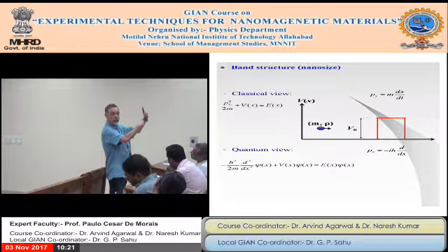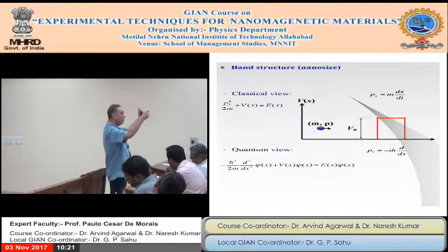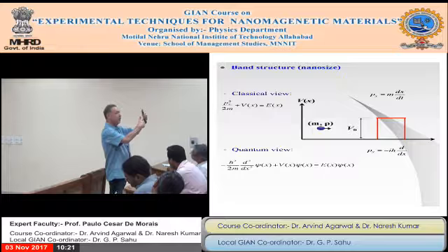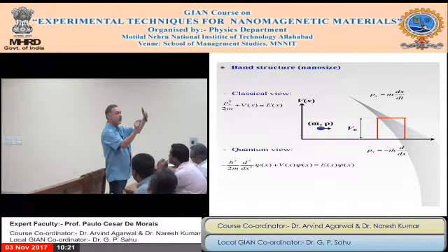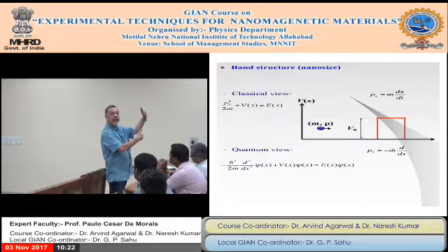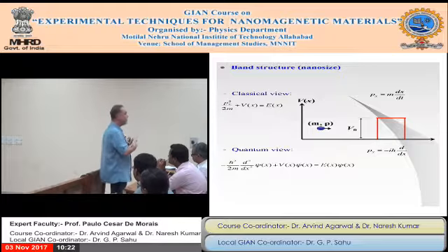Then you fabricate a very small particle of silicon. The effective band gap is not like this much anymore, it's higher. And as you squeeze the size of this silicon nanomaterial, it goes higher and higher. So it is a way to modulate the effective band gap. It's what we call band gap engineering.